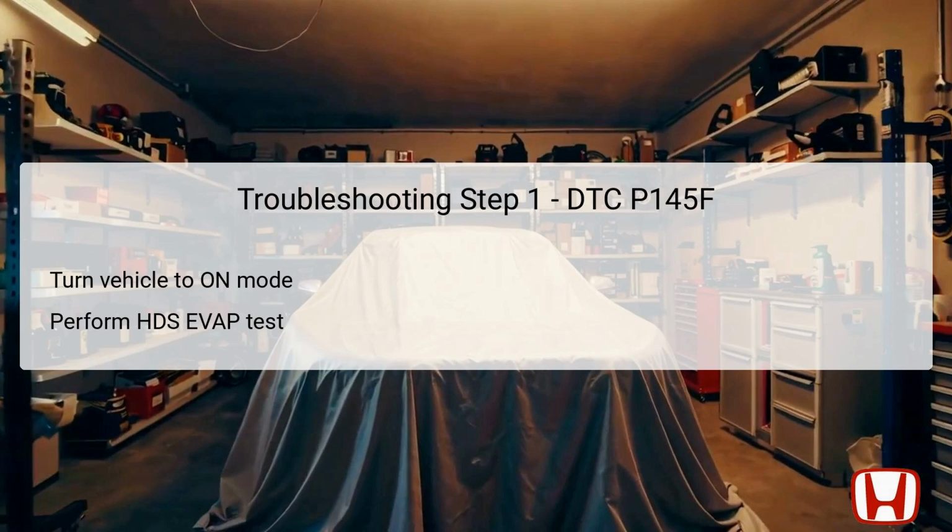as it will guide the technician on the subsequent investigative actions to take. The next troubleshooting step involves a hands-on approach to inspect the ELCM system. Begin by disconnecting the drain tube from the EVAP leak check module. This step opens the system for further examination, allowing you to directly assess the functionality of the components involved.